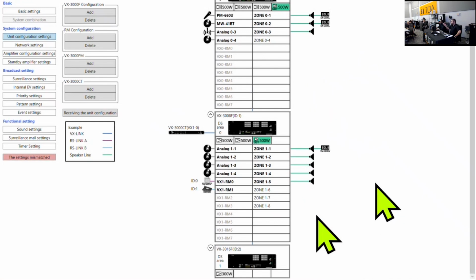But for the end of line, you need to purchase the module for that. So some countries require that. For basic monitoring, you have an impedance measurement of the speaker line, so you can detect short or open or some deviation from the previously set up impedance for the speaker line. But there are also modules, which need to be a special order, for the end of the line, so it can be monitored as well.